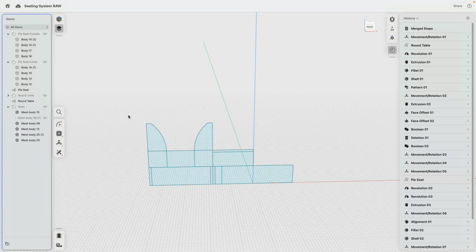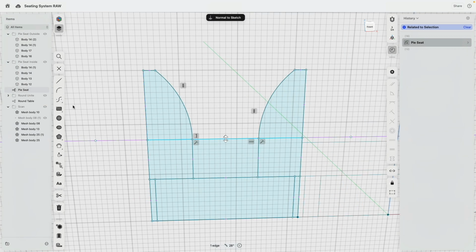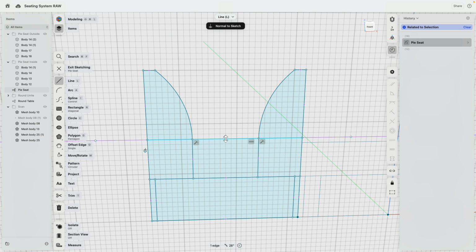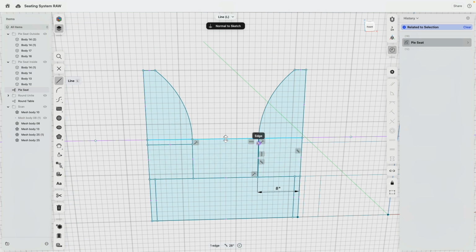And that's super easy because we saw the seat that is arced has a flat piece here that's as wide as the backrest. So I'm going to put this still into our sketch here. So there, click, and I only need to do this on one side because we can just mirror the sketch.